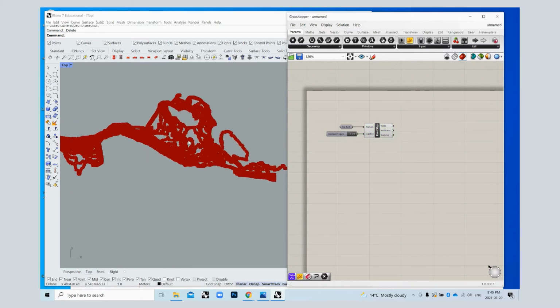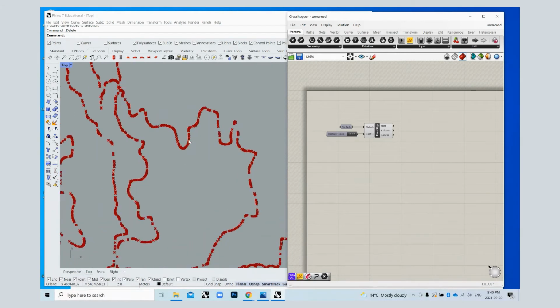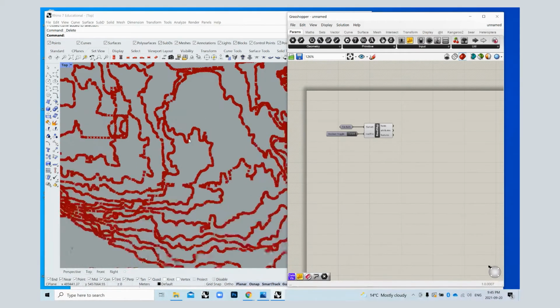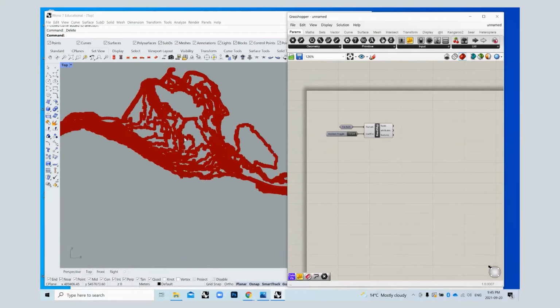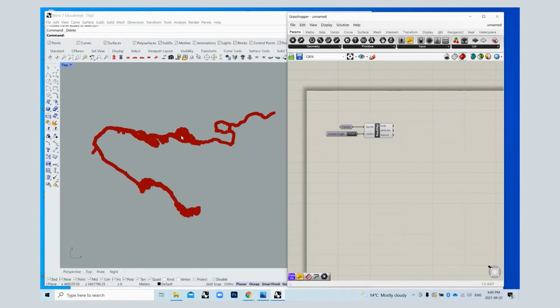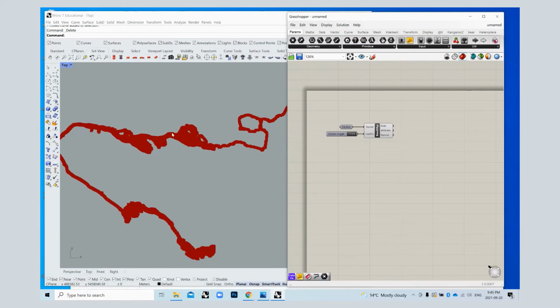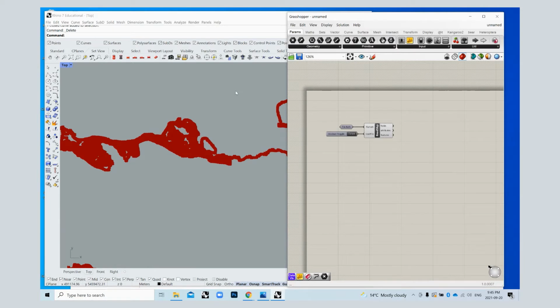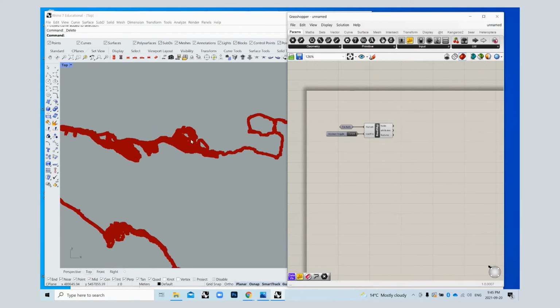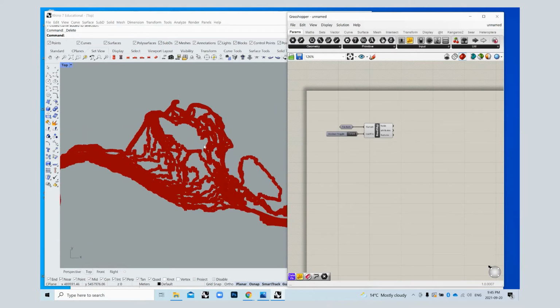Now, you might be noticing that these are actually points and they're not connected. So we're going to need to connect them using a polyline. It also comes in with the full length of the contours that are extending past your little block that you've chosen, but we're going to trim those out after. And remember, if I click, it's going to know that I'm selecting it. If I'm not clicking, and I also can't select this because it's not baked in yet.